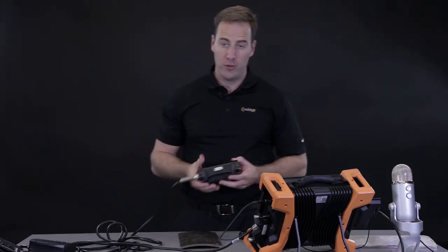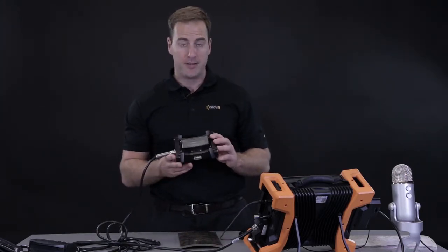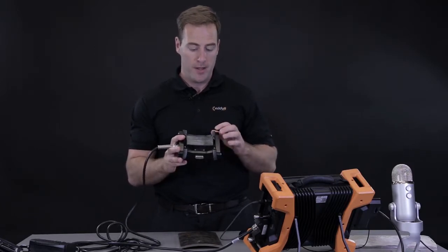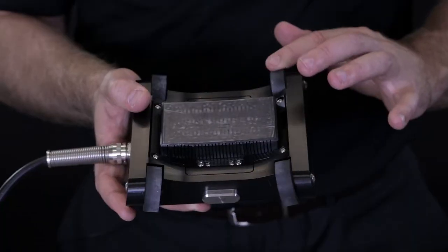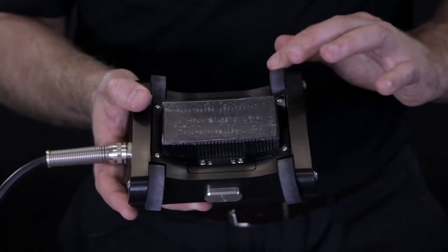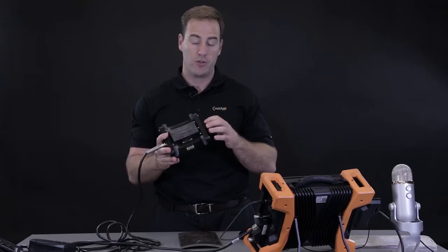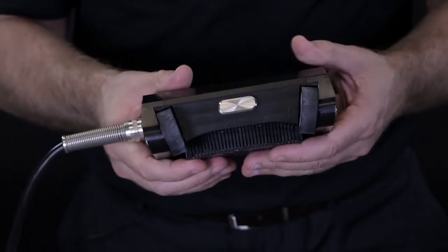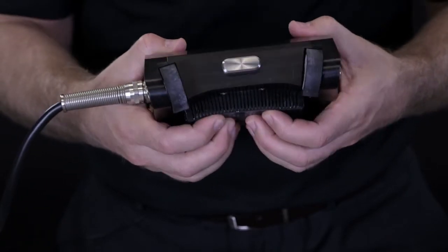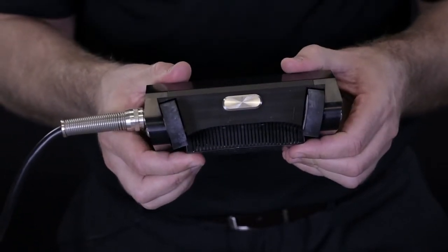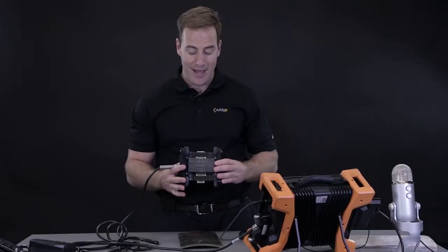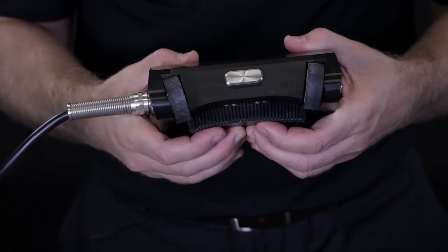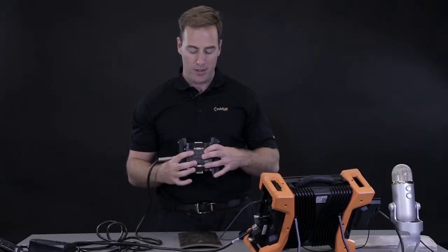So a few details quickly about this design. Once again, there is an encoder integrated in the probe body. These two wheels here are attached together, and the encoder is linked to these wheels. We also have a spring-loaded shoe like that, in a way to keep a constant pressure under the probe during the scan. And also, this shoe can be bent to fit the pipe diameter.